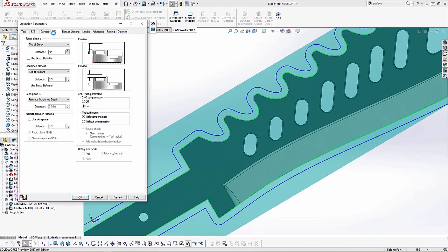wear offset. So if you had a 1/4" tool, you would measure the distance or the diameter difference from nominal, how much has the tool worn, and you would put that in as your wear offset. But nowadays, more people are using probe systems, such as the Haas system, that wants to default to using the full radius of the tool.